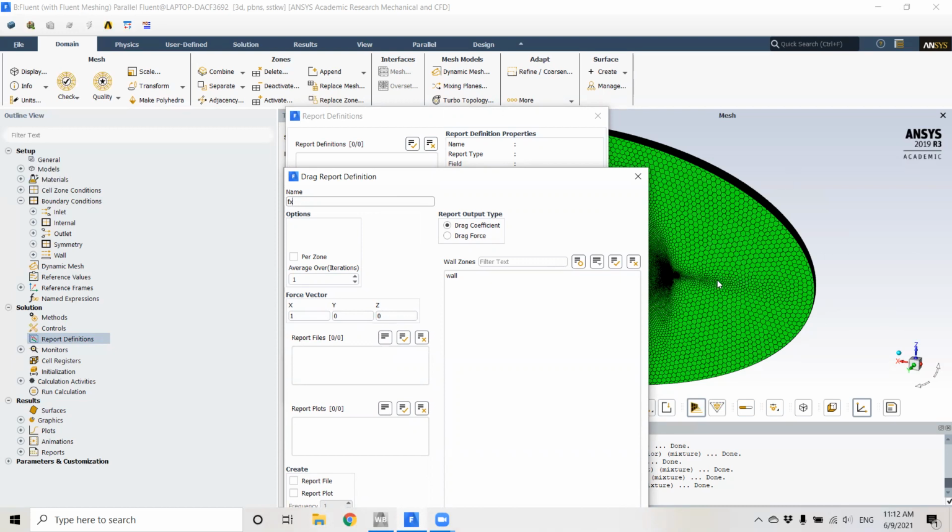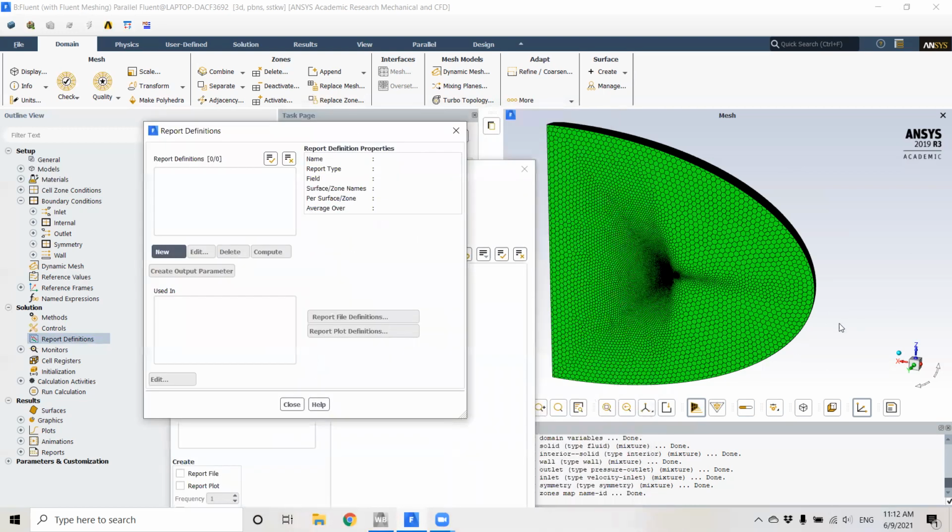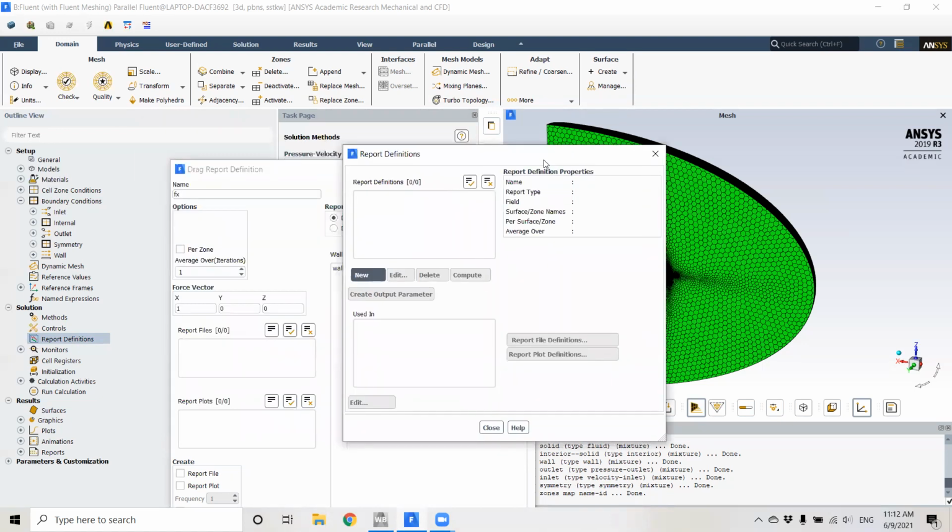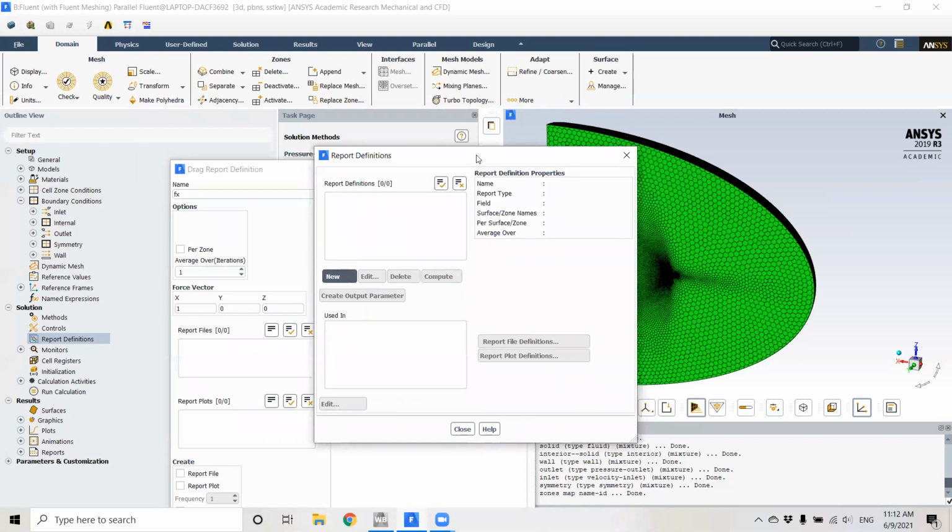And if you have, for example, an angle of attack that is like this, like the fluid is coming in this direction, you're having forces Fx and Fz, and then you gotta decompose those forces into the actual drag and lift by applying a coordinate transformation from the body system to the wind system. But that's a conversation for another video. For now, let's call it what it is.